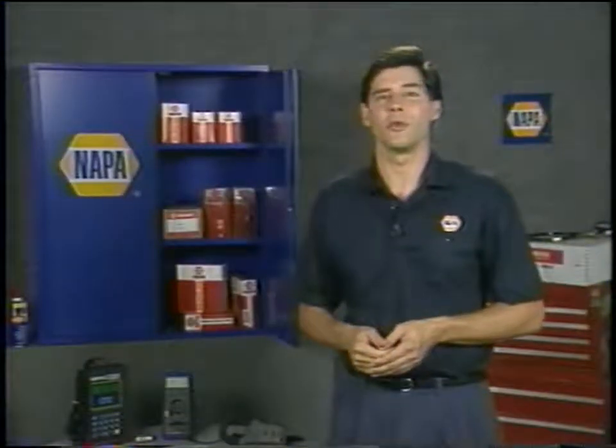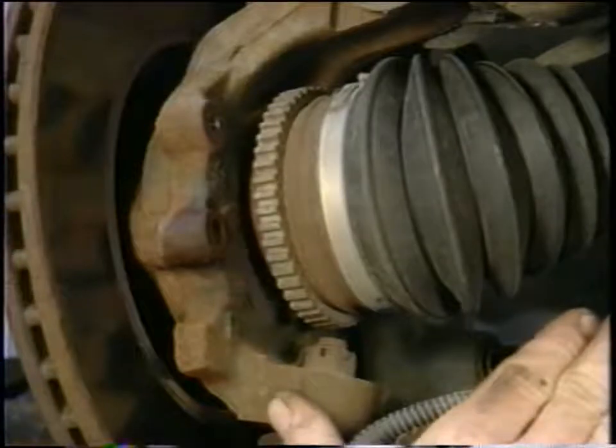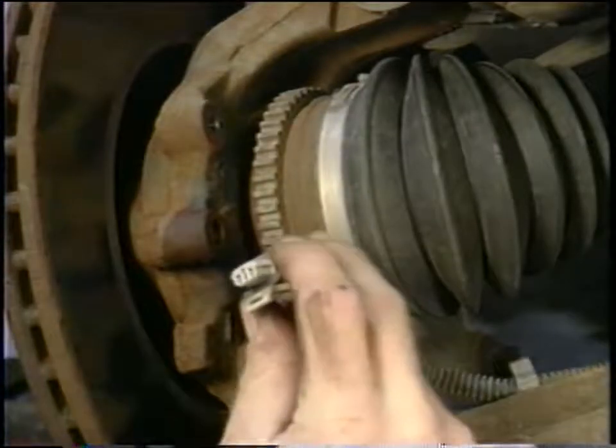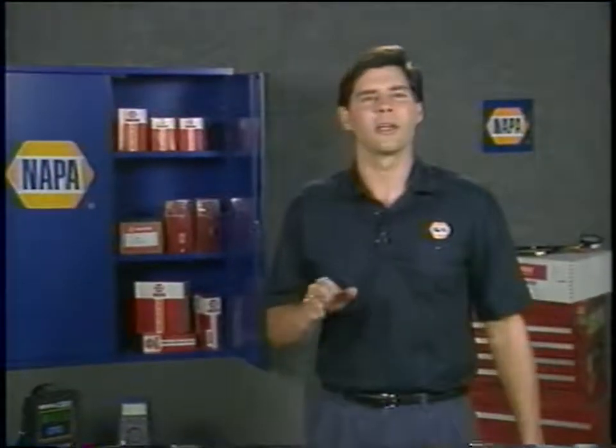When replacing a wheel speed sensor, be sure to inspect the sensor ring for damaged or broken teeth. If the ring is defective, it too must be replaced. Also, inspect the wiring and connector. Make sure the connector fits tightly and is free from corrosion. Right and left, as well as front and rear sensors on many vehicles, are not interchangeable, so make sure you have the correct sensor for the application.